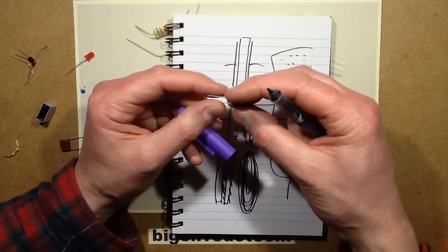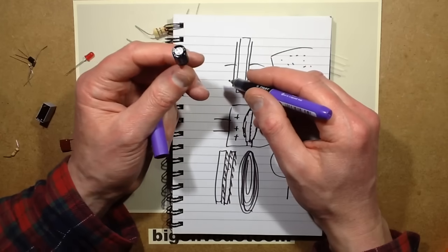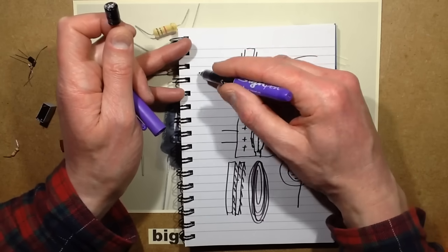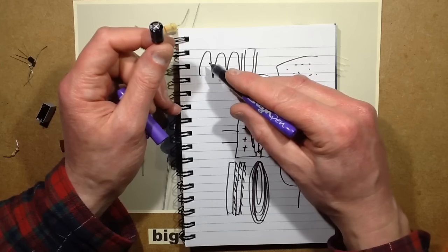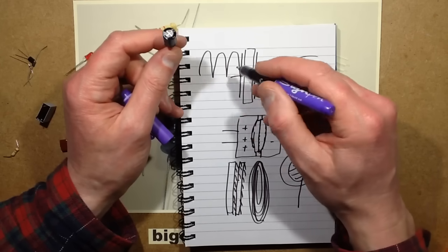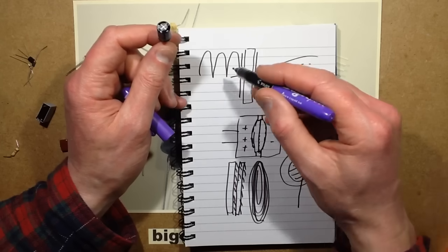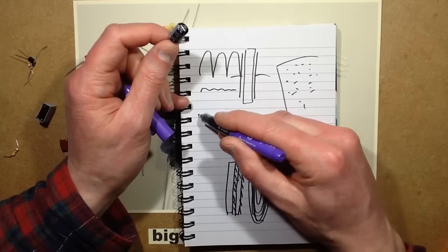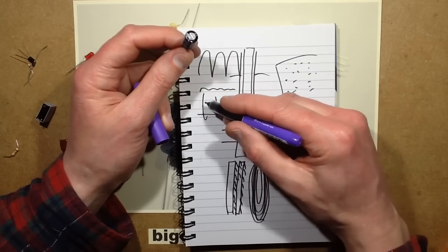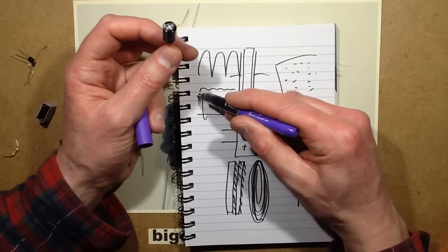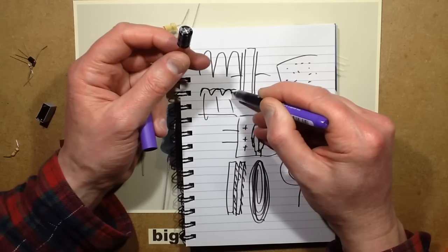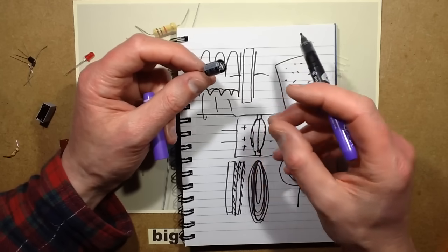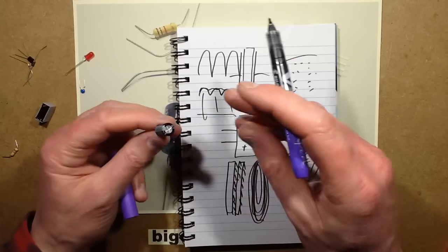When you get the large values like this, they're usually used to smooth ripples. So say for instance you had the output from the mains rectified, and you had a big peaky full wave rectified AC waveform, which is like the two sides of a sine wave. Then by putting this across that, it reduces it to a very slight ripple and a nice smooth DC voltage. And as that capacitor dries out over time, that ripple will get bigger, and it ultimately starts causing problems when it dips down so low that the electronics can't sustain normal operation. And that's when you have to change capacitors.